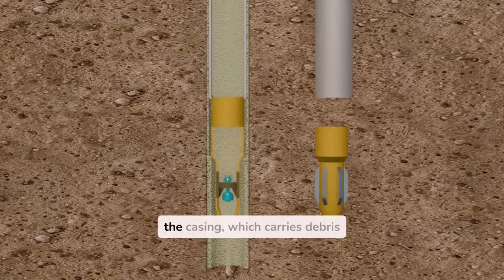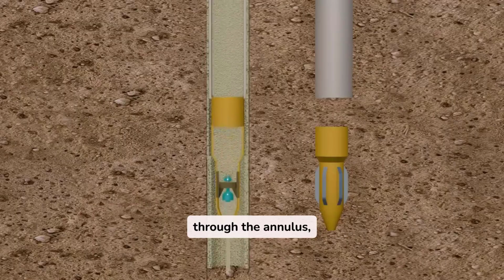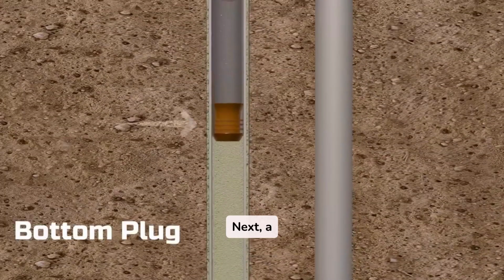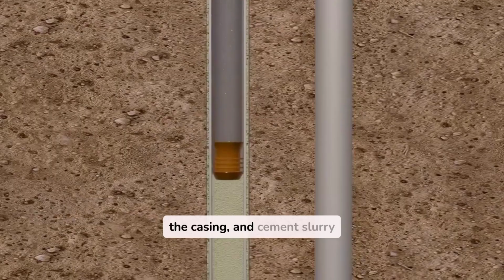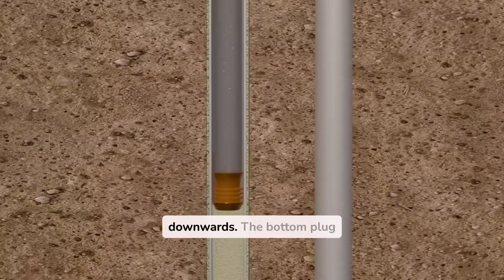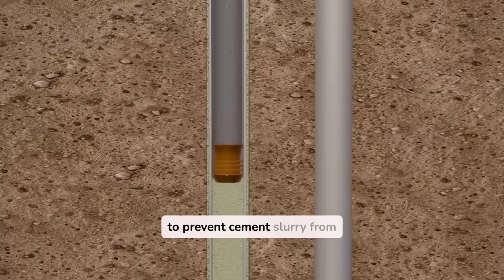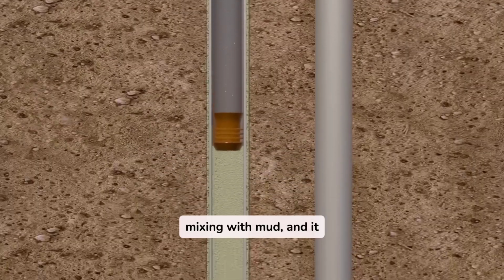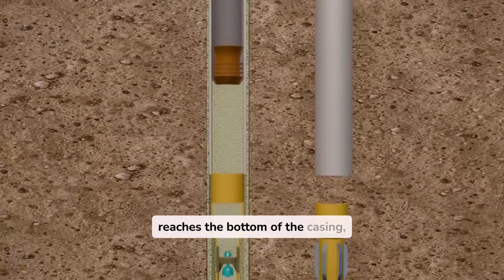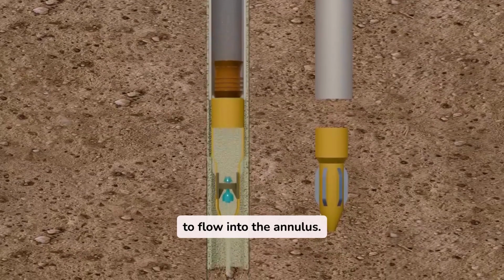First, mud is pumped through the casing, which carries debris from the bore and pushes it out through the annulus, effectively cleaning the borehole. Next, a bottom plug is inserted into the casing and cement slurry is pumped in behind it, pushing the bottom plug downwards. The bottom plug serves two purposes. It cleans the inside of the casing to prevent cement slurry from mixing with mud, and it forces mud out through the annulus. When the bottom plug reaches the bottom of the casing, it locks in place, allowing cement slurry to flow into the annulus.